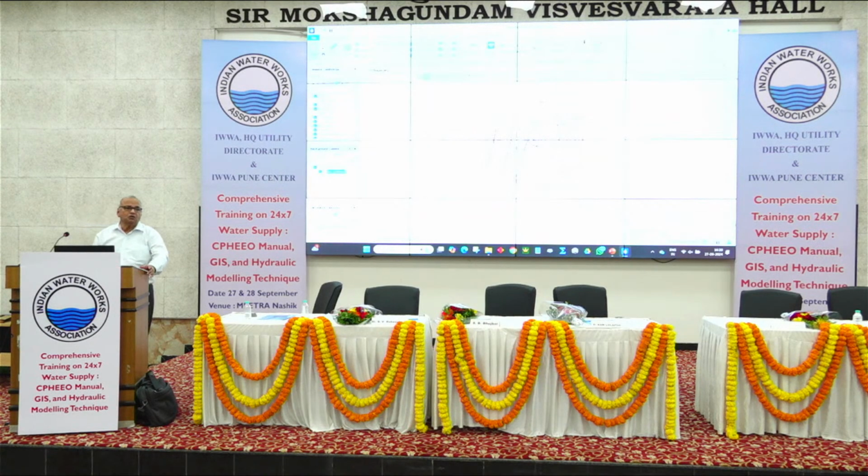From contours now, all the nodes must get the ground elevations. And there is a facility in WaterGEMS called TRex or Terrain Extractor. Using this facility, we can assign the level data from your contours to the nodes of your distribution network. How do we do that?